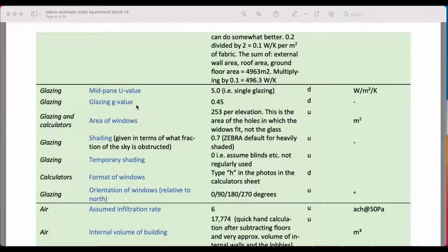And things that need to be accounted for are things like whether the occupants use external blinds, whether the windows are recessed back into the building fabric quite a long way, and therefore there's a lot of shading from the head of the window. How much of the window is actually glass? It's very common for 40% of UPVC glazing to actually be plastic, not to be glass.